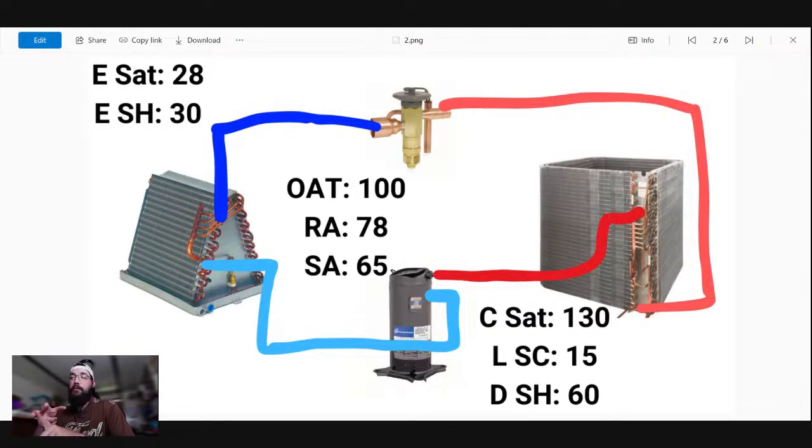You did a visual inspection on the liquid line itself, and you couldn't find any visible kinks. The majority of the line set was accessible to some degree. Obviously, not everything is always going to be, but in this particular case, you were able to get there. You could not identify an actual kink. And by checking liquid line temperature at the condenser and liquid line temperature coming into the valve, you'd only lost maybe 1 or 2 degrees.